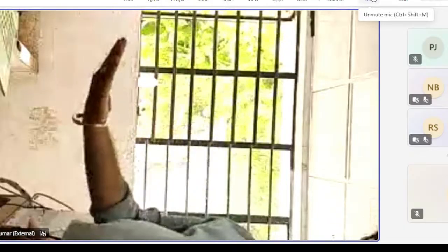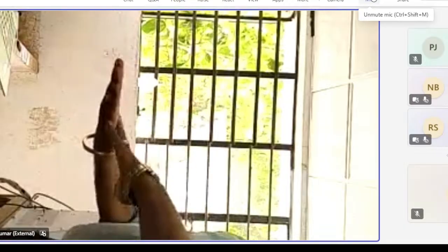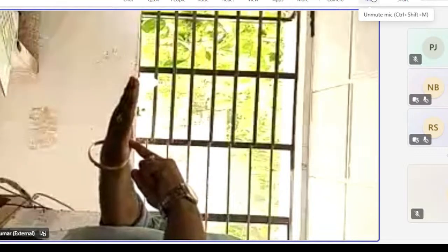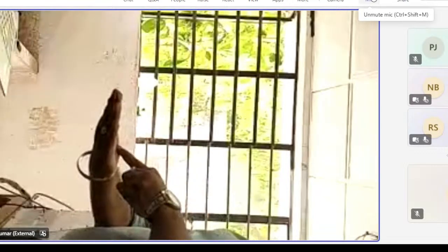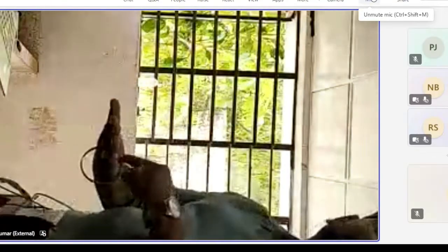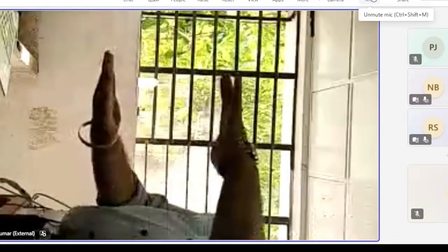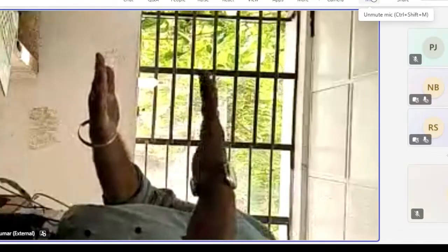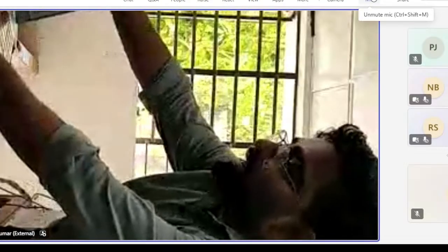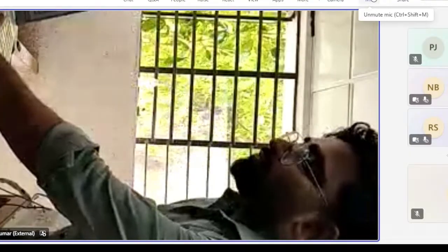Next, suppose we want to deposit only a single bead and just stop the program directly. What will happen if we stop directly over here? There are chances that there will be a weld between the wire and the already melted material. So firstly we deposit a bead, then move the tool upside, and after that we stop the program. So the program is showing that M3 is starting the torch, then after that we move X80 with a speed of 4 mm per second.